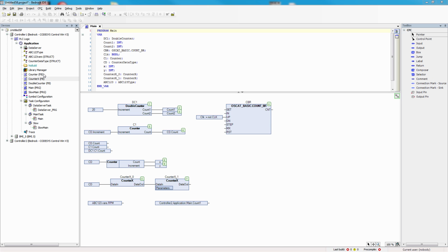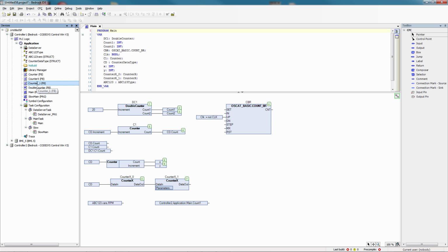Now, counter is kind of a generic example here. Think more of like if you have a skid with pumps on it. You have a 1 pump skid and a 2 pump skid and maybe a 3 pump skid. How can you extend the functionality of that 1 pump skid without duplicating the code that's in your 1 pump skid? So we're going to use, as I said, a counter. We're going to make a copy of the counter here, and we're just going to call it counter 1.